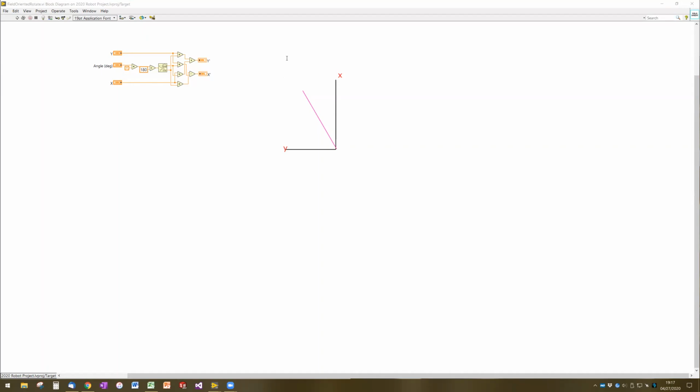Literally, all this math does is rotate your X and your Y so that they're lined up with the direction that the robot's pointed. And this becomes your X. That little symbol in math is often used to say prime, so it's X prime, and then Y prime. So you could do it a couple of different ways, but essentially you are just rotating your coordinates so that they're always pointing the same direction as the robot's pointed.